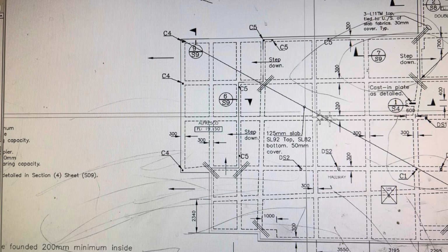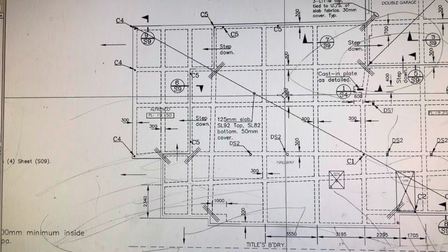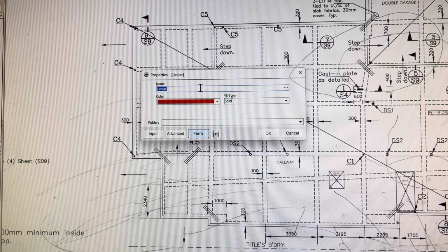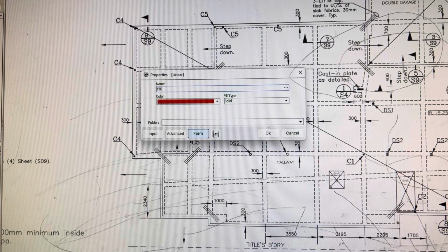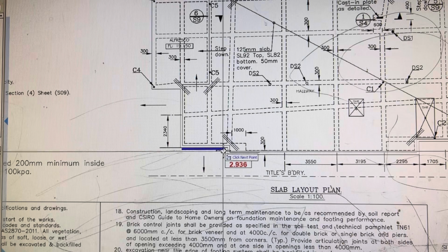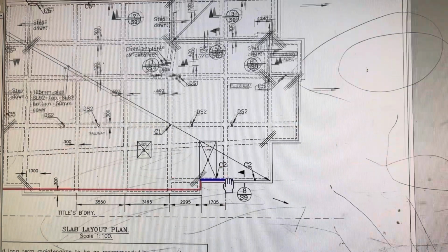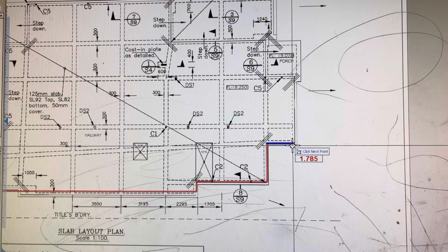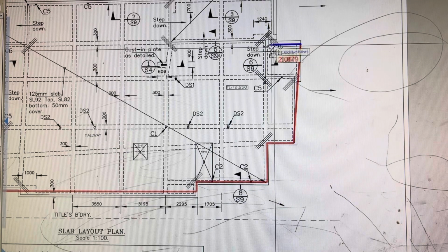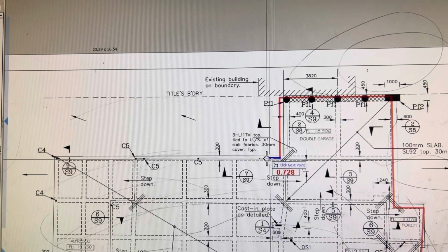We'll trim it out. Now we want to know the edge beams or external beams. You can call it EB for short, abbreviation for edge beam. Why we need edge beams and internal beams is to calculate the quantities of concrete and steel. So that's the edge beam.